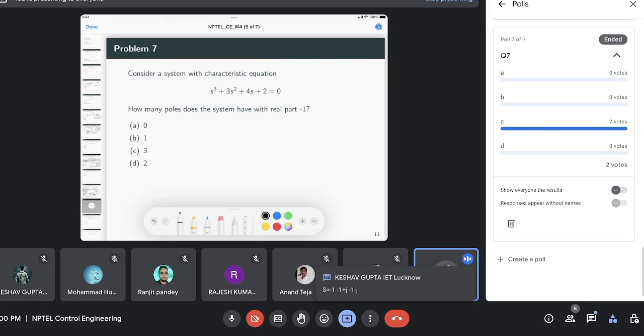So one way to analyze will be shifting that. As you already know how to find the imaginary axis poles, right? If you have a row of 0, then whatever follows, it is possible that it can have imaginary axis poles. If there is no sign change, then for this auxiliary polynomial there will be no right half plane poles.